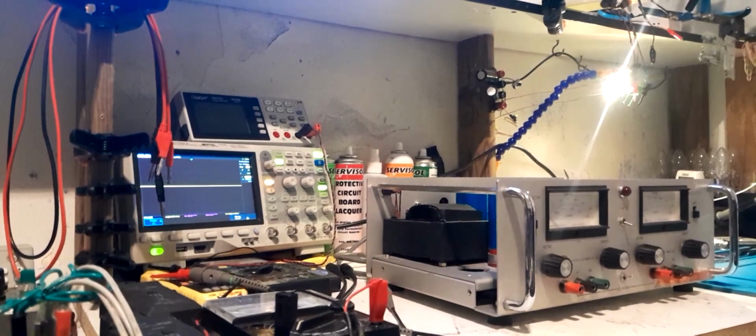Because to be honest, it could actually be either one of the two things happening. It also could be both an op-amp and the reference are oscillating, and there are waveforms of both interlaced onto each other. So I think I'll just stick a zener in there and just see what it looks like, just for curiosity.